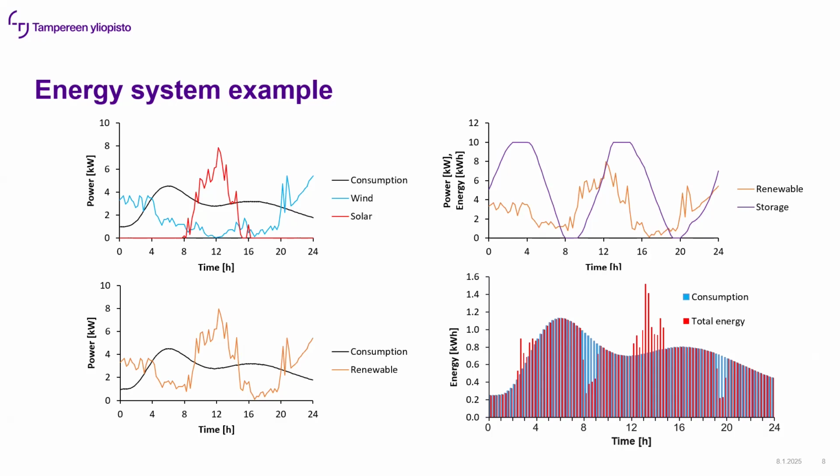And in here, you can see that there are certain aspects that I have to take into account. I have to take into account production modeling. I have to take into account the consumption profile, and then I have the energy store. So that's really a simple system. And the energy storage, I can model that if in the previous hour I have a surplus of energy in here, then on the next hour I have, of course, that depends on how much charging capacity or charging power you have in the battery. But that's available later on to be used in the model.